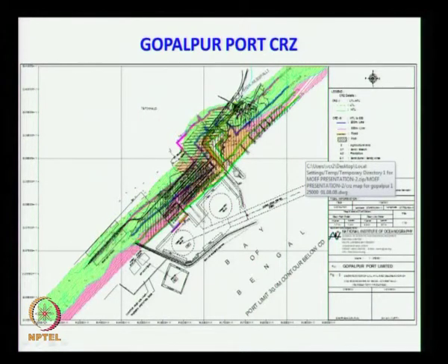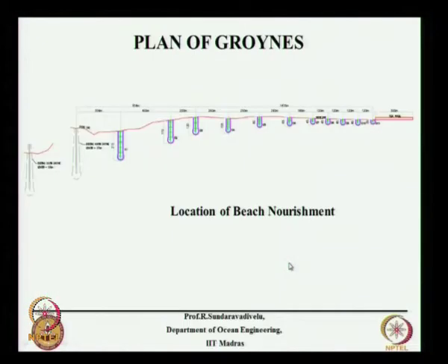This is the groin which is built for the inlet, these are the 9 groins, beyond that we will have the sand trap. This is what is actually now being built now, these are the inlet groins, these are the 11 groins, the distances are shown here, this is the seawall which is shown here. These groins are built 50% now. Now they will be stockpiling the sand right up to this toe of the breakwater.